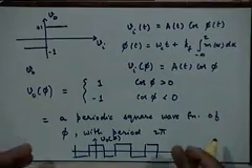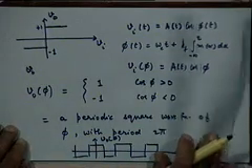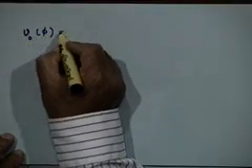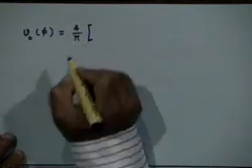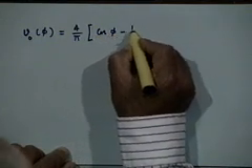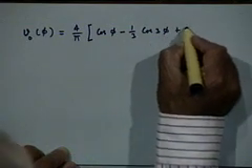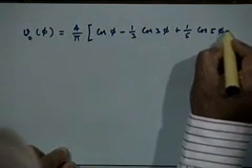And I know what kind of a Fourier series a square wave function has, it contains only odd harmonics of the argument, right, and the precise representation is as follows. So, V naught of phi, which is the square wave function, has this Fourier series representation: 4 by pi into cosine of phi minus 1 by 3 cosine of 3 phi plus 1 by 5 cosine of 5 phi and so on.